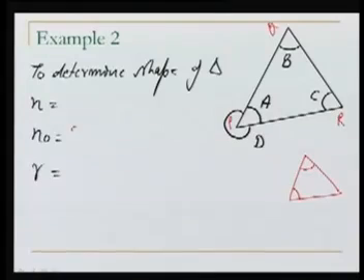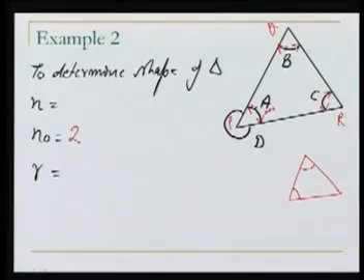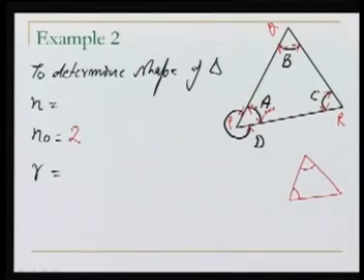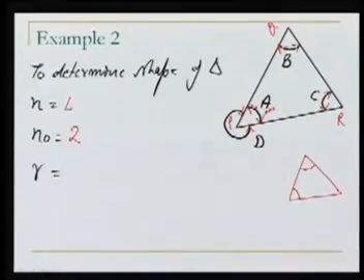But someone who was working in the field observed angle A, angle B and angle C also. So basically A is the observation, the value for angle QPR. At the same time, he also introduced more redundancy. He also observed angle D. He closed the horizon there. So the number of observations which he has taken is 4. In this case, the redundancy in our model is 2.